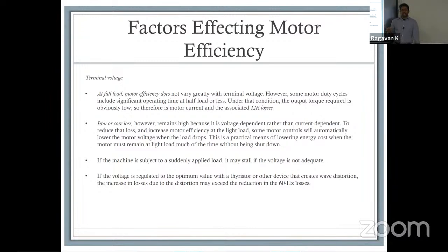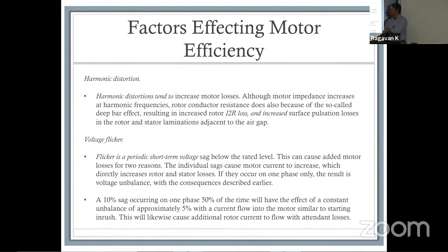If you have ever used a hairdryer or a heater while a light is on, you will see that voltage dim. That's the voltage drop or voltage sag you're going to experience. So you really do need to think about, in our case, 60 hertz, in your case, 50 hertz. You need to look at specific losses that you can have in terms of your system.